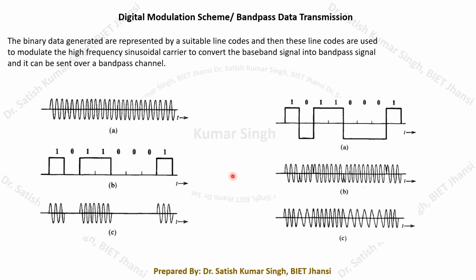Because when we send the signal, it takes low frequency components. If you remember, I explained the rectangular pulse, whose Fourier transform is the sinc function, which varies from 0 to 1 upon TB, its major lobe. That portion is taken for calculating the bandwidth requirement. These pulses contain the basic low frequency components when we reject all the other high frequency components, and therefore it is referred to as a baseband signal, and we use a baseband channel, like a wired channel, for transmission of this signal.